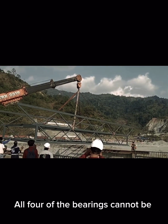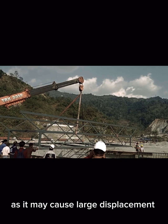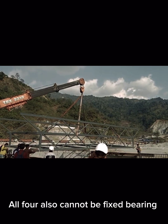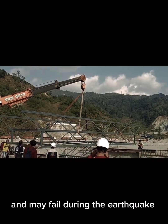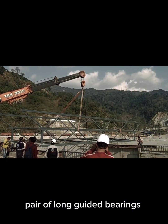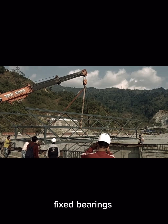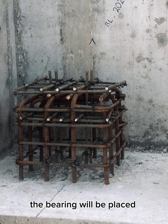All four of the bearings cannot be long guided bearing, as it may cause large displacement. All four also cannot be fixed bearing, as there will be no displacement and may fail during the earthquake. Hence, one abutment should have a pair of long guided bearings, whereas other abutment should have a pair of fixed bearings.